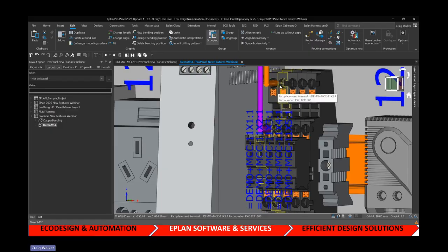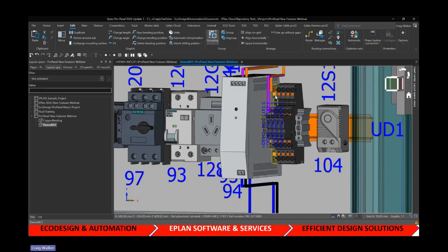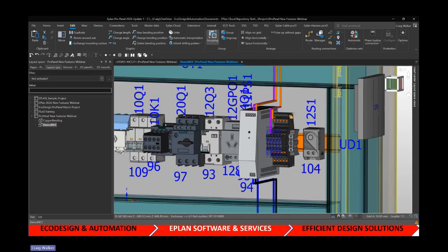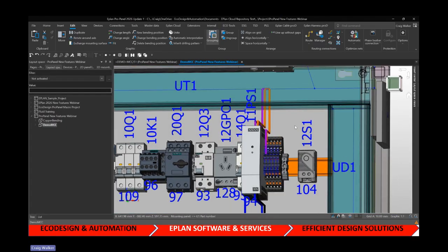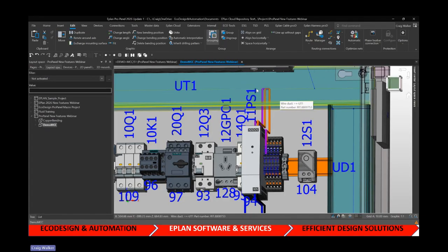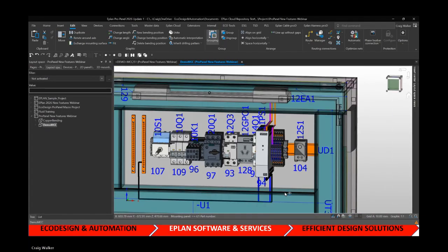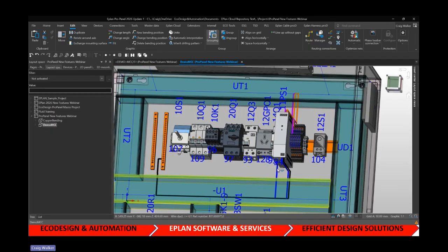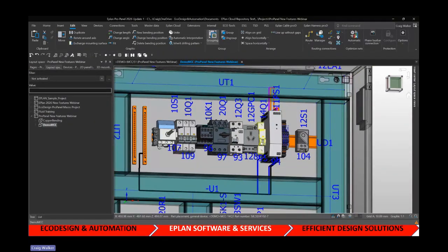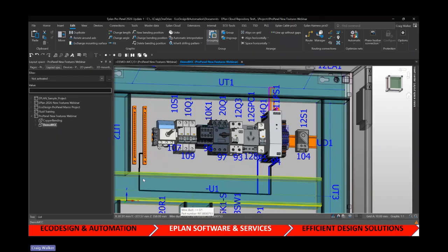There are 2 different locations for the connection point designations on those, and they're routed upwards too. So it knows to come up into this duct and then back down through this routing path. At the bottom, you can see the connections from that are routed to one phase from the breaker and the other phase from the neutral bar.